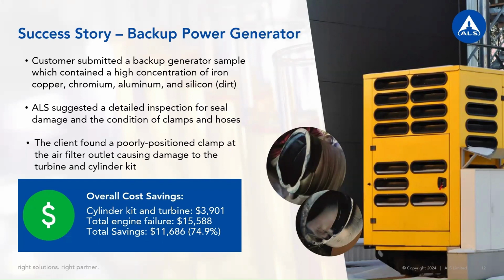We knew what their units tended to look like analytically, so when a sample came in with a high concentration of iron, copper, chromium, aluminum, and silicon, it was immediately flagged. Our diagnostics team suggested a detailed inspection for dirt ingression to the system and to check the cylinders for wear.